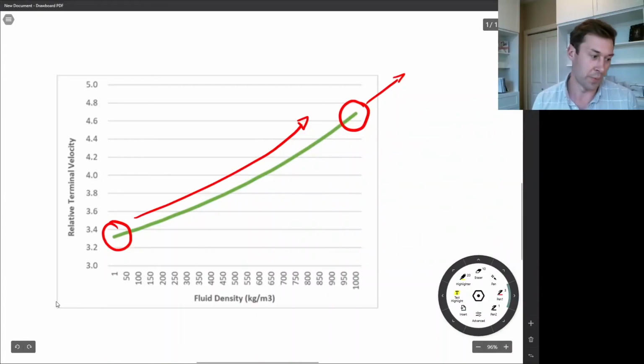So these increases in relative velocity between the heavy or dense particles and the light particles also make separation easier. And to the extent that even more viscous fluids can be used, so if you have a lot of, let's say, very fine particles in the fluid and it creates an artificially dense medium, and the density goes even higher, this gap will widen and the relative velocities between those particles will become greater and separation will become easier.